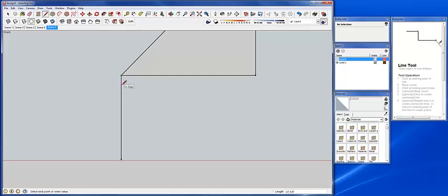One of the really nice things is there's no overlapping function. So if I hit 6, this is set to inches, so I'm just going to go 6 inches down. And so it'll never replicate geometry. If something overlaps, it'll just split the existing geometry over that. So then this was, if we look at that, 8 inches wide. So that's our first guy. And we come in. Our column here is 1 inch over. And pull that down. And we'll hit space and then line to reset the tool. That's 1. And we'll pull that down and we'll navigate so that's over.